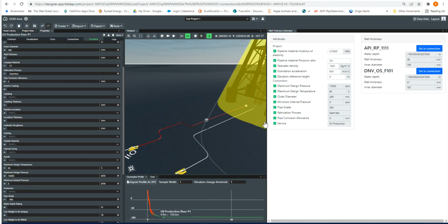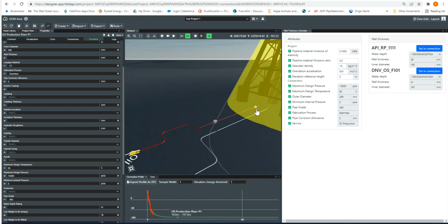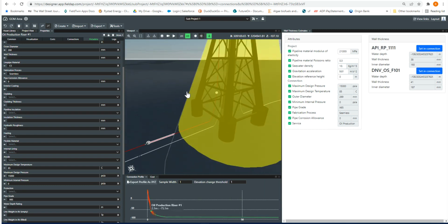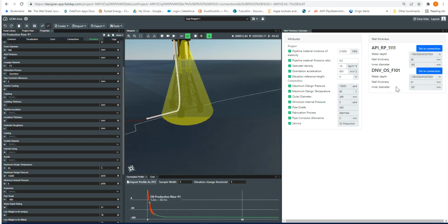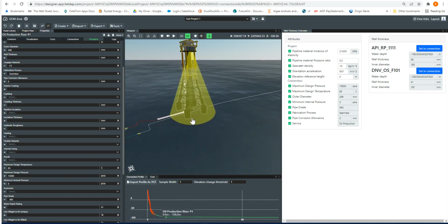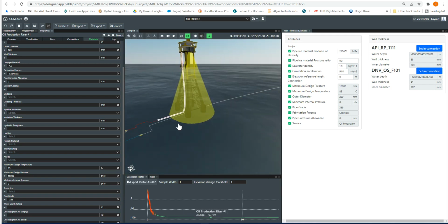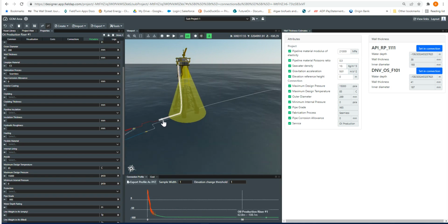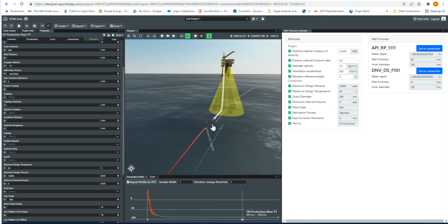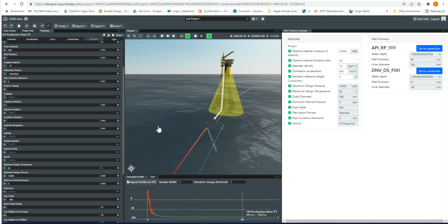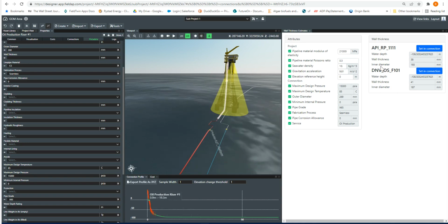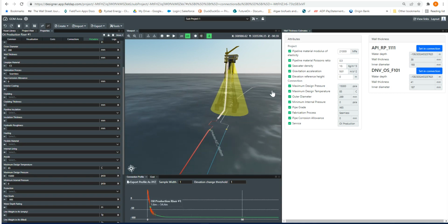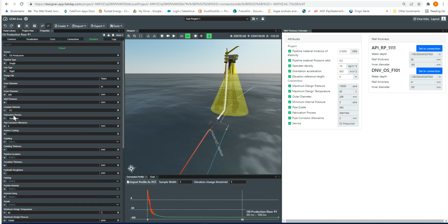And it did not. Well, I know if you declare the type to be riser, it should detect it because there are different partial safety factors in DNV for risers. But I know it's been done on a deep water host. So my apologies for picking a project that does not have a deep water host, but we'll have a second tutorial that will show that the tool can distinguish when it's a riser and will use the appropriate DNV partial safety factors for risers. But that's really beyond this initial discussion.